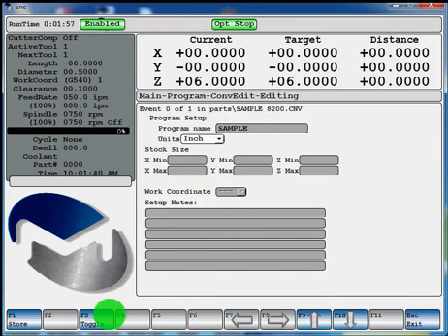You're going to have F3 come available here. You can toggle through either inch or metric. We'll program in inch. And hit Enter to come down to your solid model stock size. So for this example, we'll say we're going to have a 6x6 block. X0, Y0 will be the center. So your X minimum would be -3. Your Y minimum would be -3. Z0 will be the top.